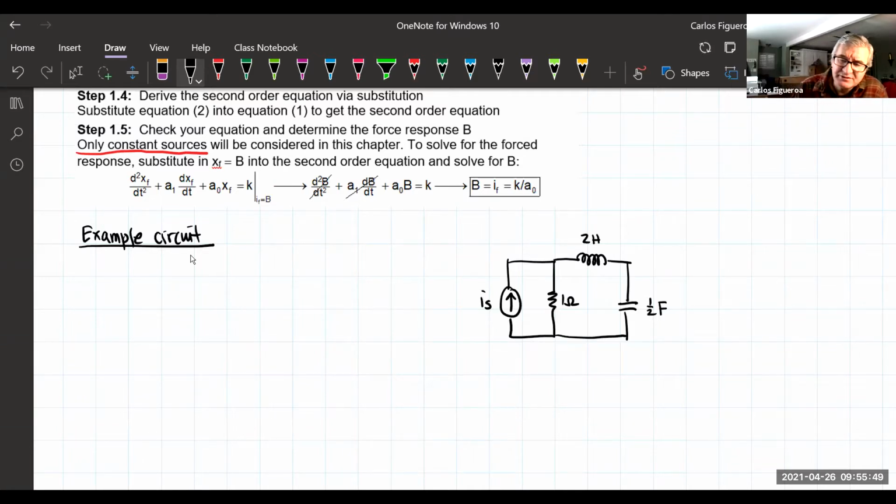So when I look at the current of how this thing is going to flow here, clearly this guy has to be the inductor current, which then means that the voltage of the cap must look like that. So here I go. Let's go do it.